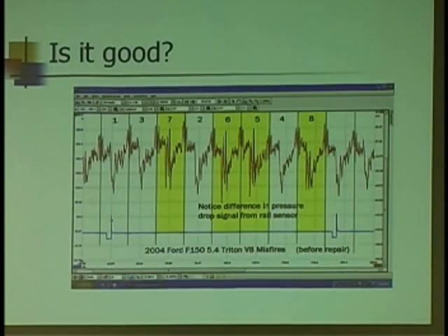I'm on the #1 injector. So right when the #1 injector opens and closes, I've got this drop. You see that? Nice, fairly smooth line. There's the drop. So right off the bat, all the drops are relatively uniform, aren't they? But 1, 3 looks kind of nice, but I get to 7, and that looked really nasty. 2, again, fairly smooth. 6, 5, nasty. 4, pretty smooth. Now 8.